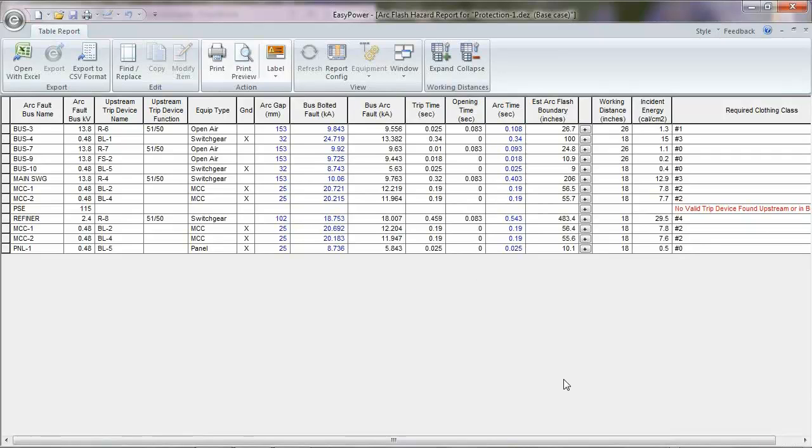If you have any questions, I did see I don't have a specific 120 volt label. I haven't been asked that question previously. I haven't supplied any labels for 120 volt systems. We do talk about it every once in a while, and I think generally, based on our arc flash, what we do is we can calculate it for 250 volts and below. The application is a little bit different, and I believe the guidelines are changing too.